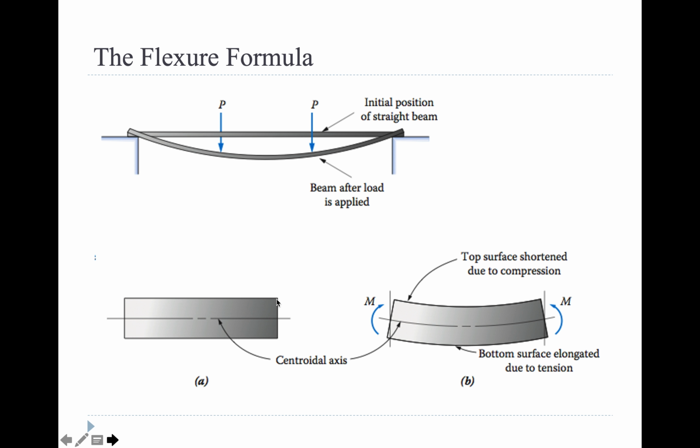Okay, and then here's like a cross section of maybe this thing that was being bent here and here with some moment that's applied on it that would be bending. Well, when something's bent like this, the bottom surface is going to want to elongate because it's getting longer down here at the bottom. You notice how in this picture, the edge is getting beyond this little constraint? Well, in order for it to bend like this, the bottom edges are having to get longer.